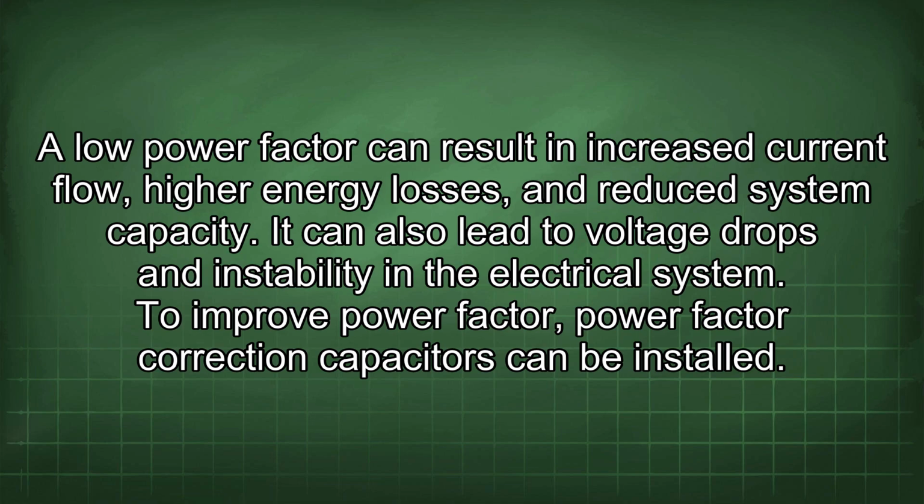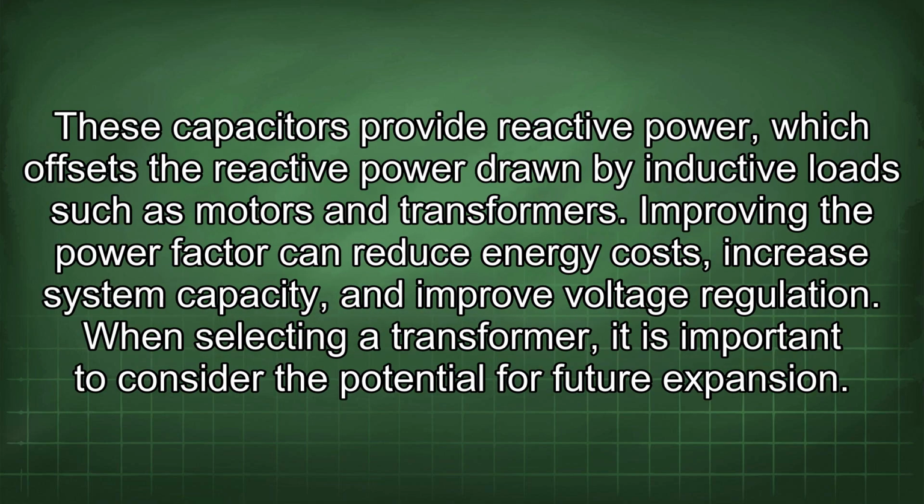It can also lead to voltage drops and instability in the electrical system. To improve power factor, correction capacitors can be installed. These capacitors provide reactive power, which offsets the reactive power drawn by inductive loads such as motors and transformers. Improving the power factor can reduce energy costs, increase system capacity, and improve voltage regulation.